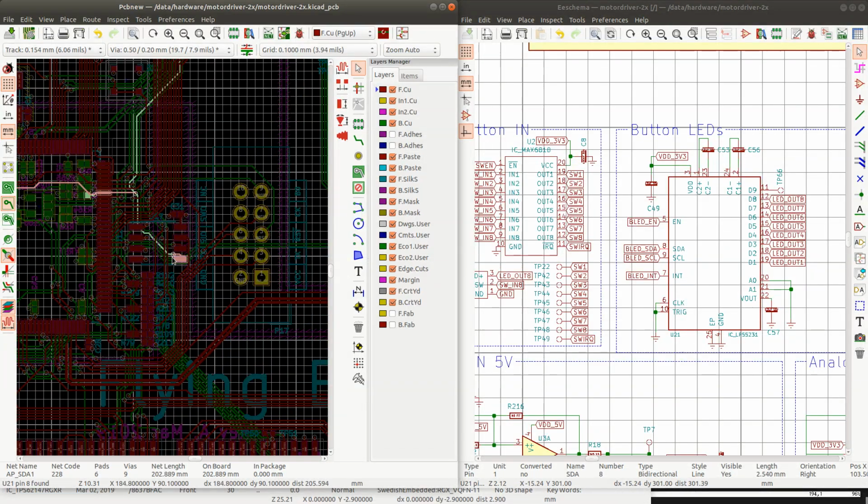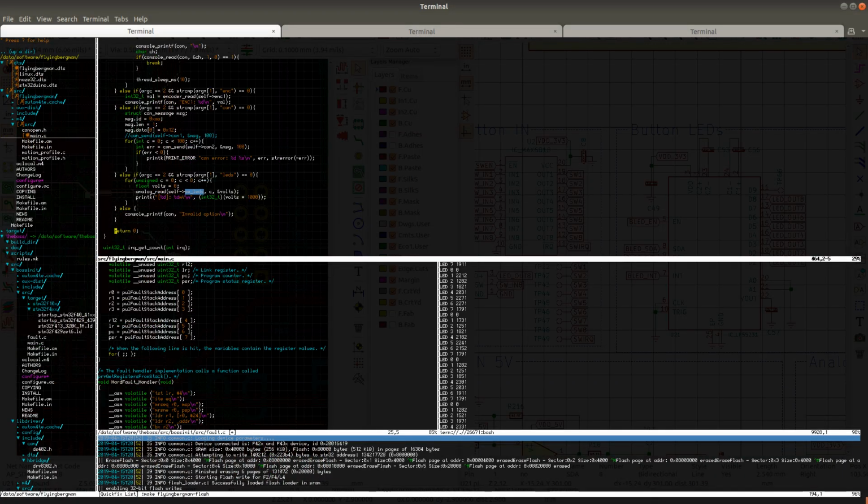I'm going to check how fast it's actually running, and maybe lower the speed of the interface. I think that according to the device tree, it was supposed to be running at 50 kilohertz, but that needs to be double checked.